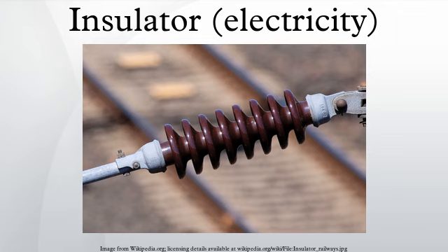Porcelain has a dielectric strength of about 4–10 kV per millimeter. Glass has a higher dielectric strength, but it attracts condensation and the thick irregular shapes needed for insulators are difficult to cast without internal strains. Some insulator manufacturers stopped making glass insulators in the late 1960s, switching to ceramic materials.